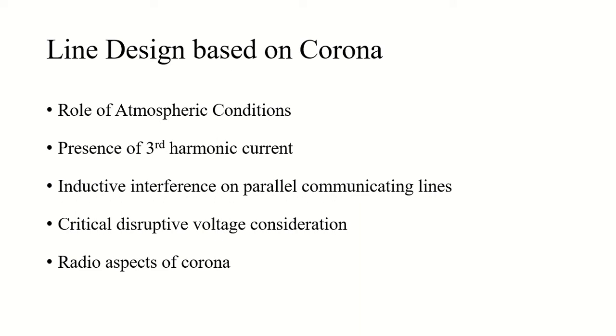And if we don't take enough care about the occurrence of corona in these lines, then the highly ionized air may cause flashover in the insulators, and because of that, heavy damage can occur to my system, particularly the transmission line and conductors. There will be damage in conductors, or even worse, there will be flashover which will harm my conductors. And the biggest disadvantage of corona is the power loss.